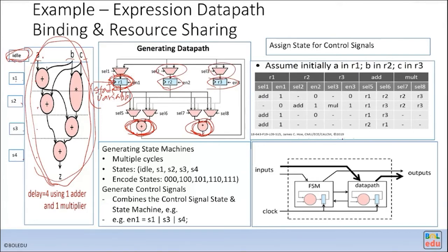For different cycles, you will select different sources. For the adder, you have 2 operands, and for each operand you have a different source coming from. For the multiplication, you have 2 operands, and the same thing, they could come from different state variables. So you roughly sketch the data path.